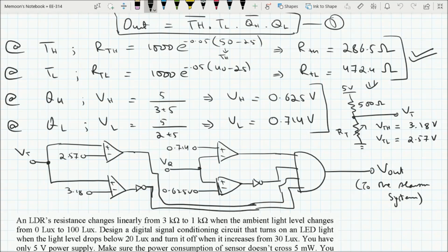And as soon as your temperature is either lower than the lower temperature limit or higher than the higher temperature limit, it is out of the range and your output should be 0. So you have to use two comparators for one parameter. And in this example, we had again two parameters and both for the ranges. So we are using four comparators for the four boundary conditions provided for the temperature and the flow rate.